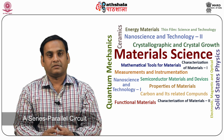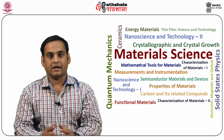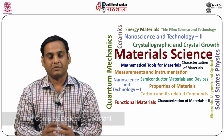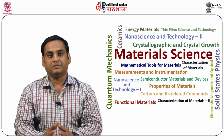Series parallel circuit. Figure 1 also shows a series parallel circuit in which a series branch having a capacitance Cs and a resistance Rs is in parallel with a capacitance Cp. We follow the same procedure to determine the real and imaginary parts of the complex dielectric constant epsilon star. The admittance of the equivalent circuit is Y equivalent equal to j omega Cp plus j omega Cs divided by 1 plus j omega Cs Rs.